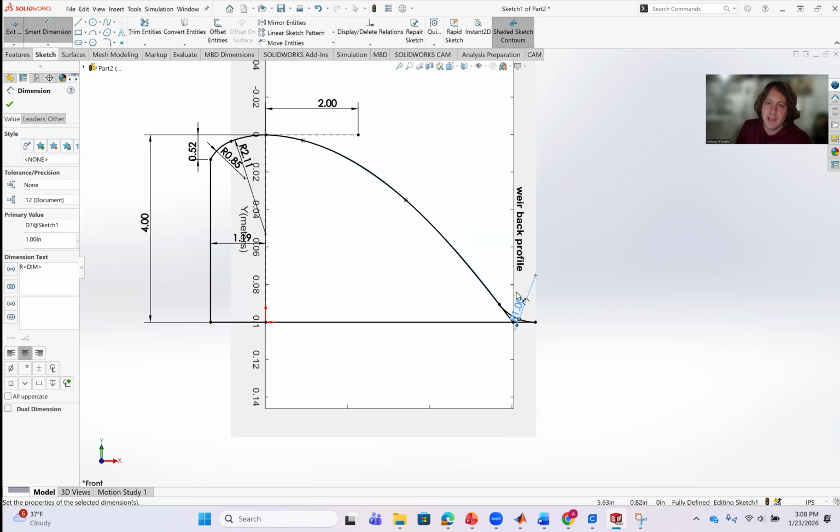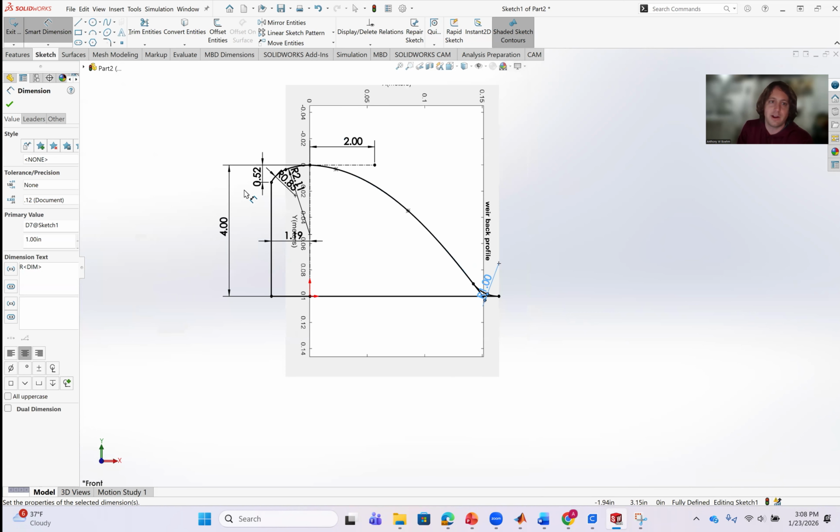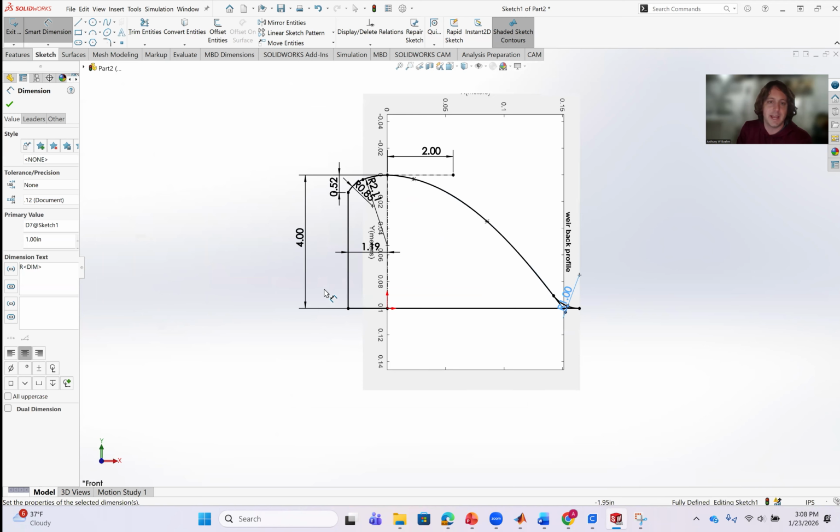It's smooth enough if the radius of it is a quarter of the weir height. All right, so put 1 inch for there. So I put 1 inch for there, obviously, because I have a 4-inch weir height. All right, so enough rambling about that little tail.